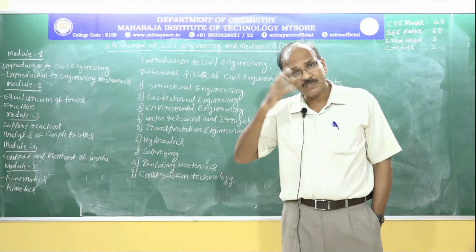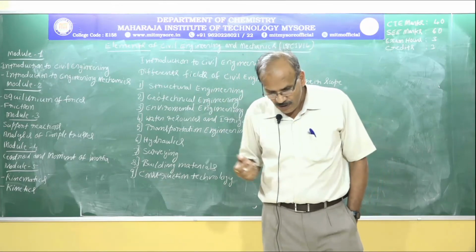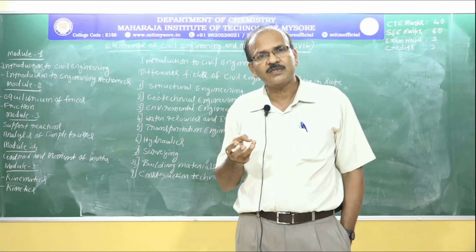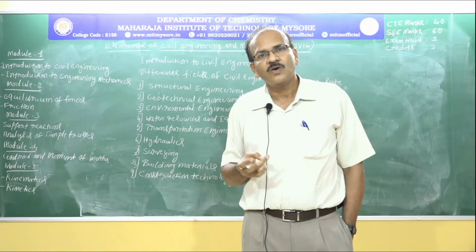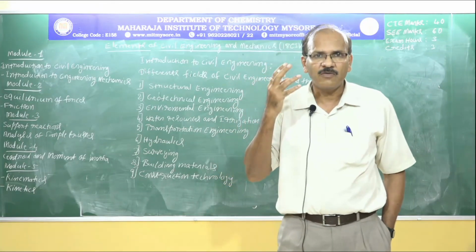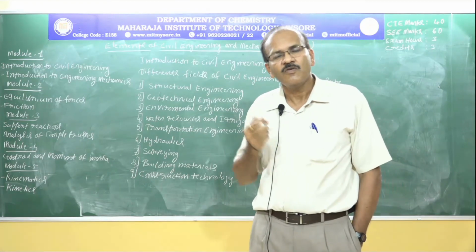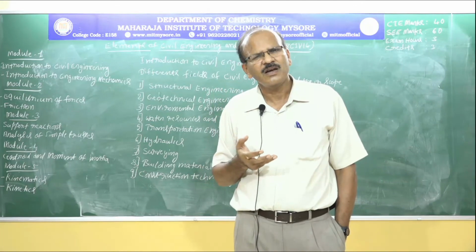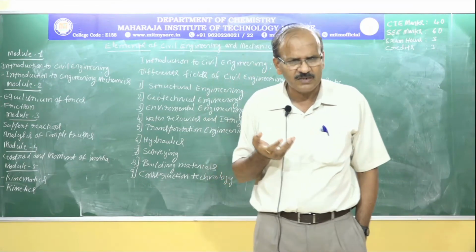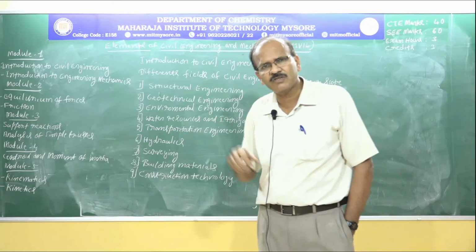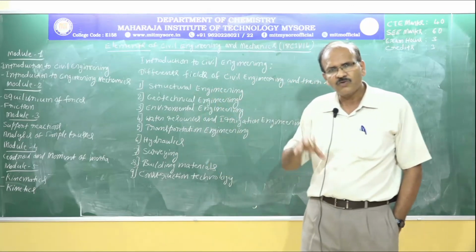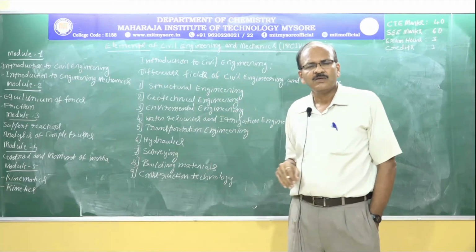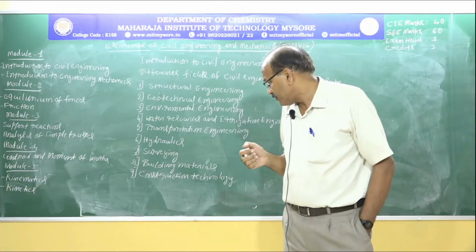Similarly, even for coarse aggregate, that is for jelly, we conduct different tests: crushing test, water absorption test, flakiness index and elongation index test, etc. Those are all the tests we conduct once you join the civil engineering field, once you start studying. You are going to study and do all these things under this subject.